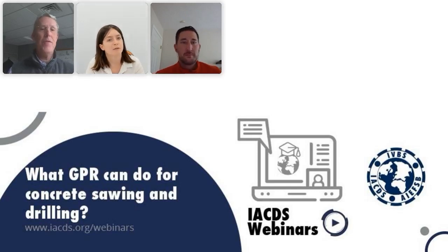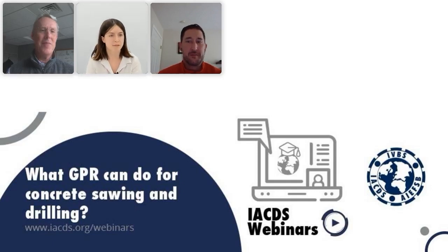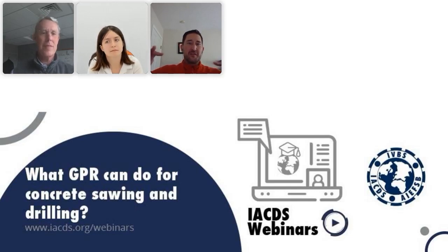Before we go, I think it'd be helpful if I asked Brett some questions, since he has the experience in concrete cutting, of times that he's had to walk away from a job site because it was just too complicated, as I mentioned. Yeah, so you'll typically run across this, especially in perhaps buildings with post-tension cables that are running along column lines. And what you'll have is several tendons coming in, or several bundles of tendons all coming in at the same column from different directions, sometimes with swoops where they're not running in a straight line.